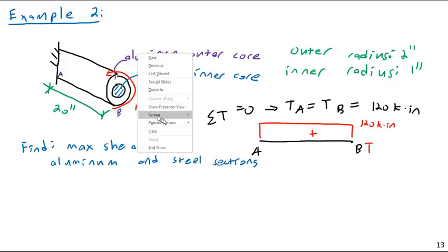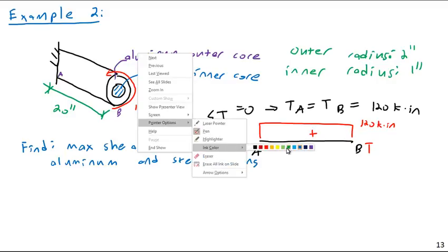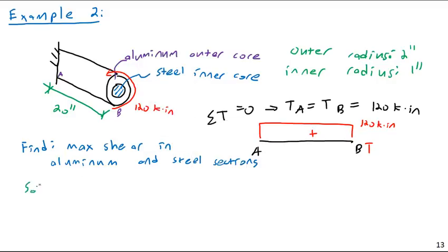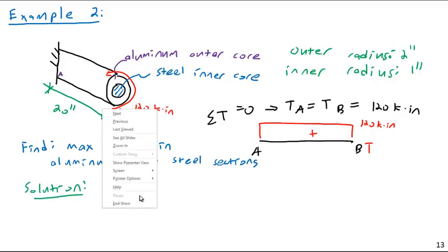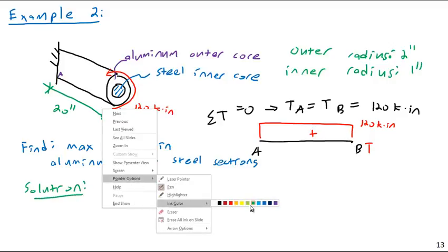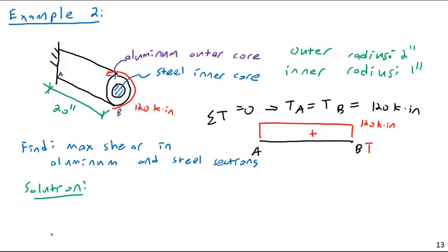All right, so we again need an equation of compatibility to solve this. And like I said, the key will be like this. The deformation compatibility equation requires that the angle of twist for each of them be the same.